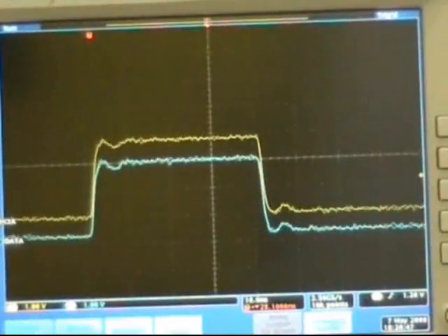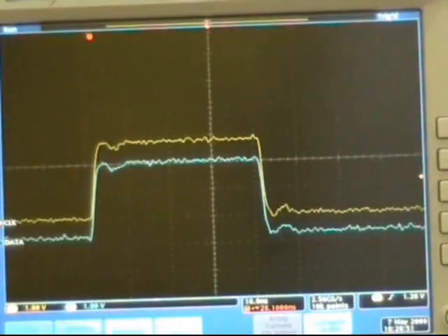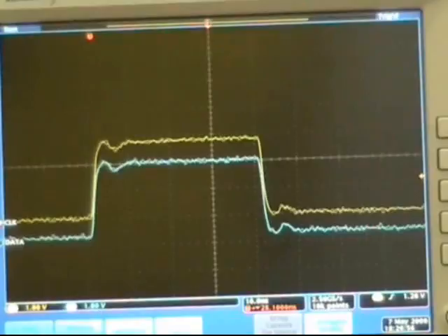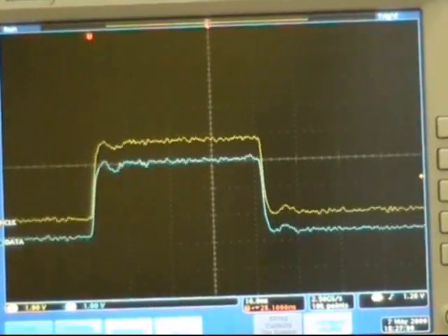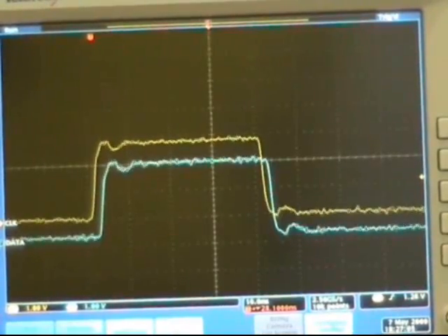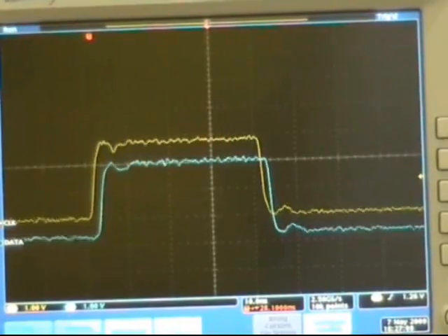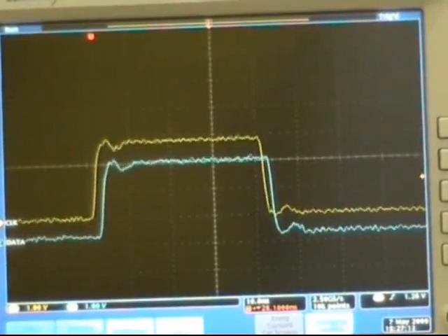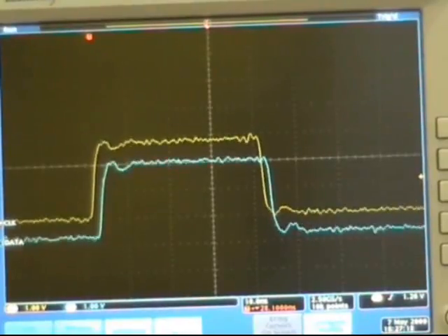Now if we program the rising edge position of channel 3 of the digital I/O module to be 7 nanoseconds, you can see that on the oscilloscope screen, the blue color curve, which represents channel 3 of the digital I/O module, is moving to the right by 2 nanoseconds. This shows the capability of the digital I/O module to be able to program the rising edge position of the digital pattern. In fact, we are able to program 4 edges within a cycle for any digital pattern.